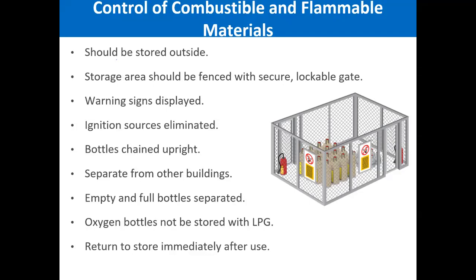Separate from other buildings. Obviously, you need to make sure there is a separation between buildings so that fire does not spread from one building to the other. Empty and full bottles need to be separated. Oxygen bottles must never be stored with LPG. And finally, you should return cylinders to the store immediately after use.